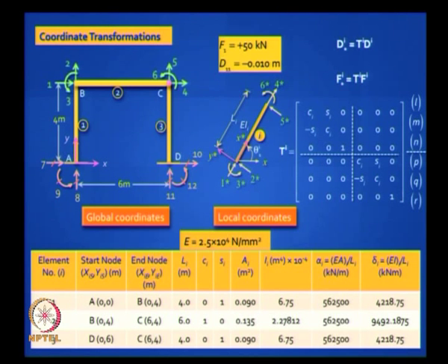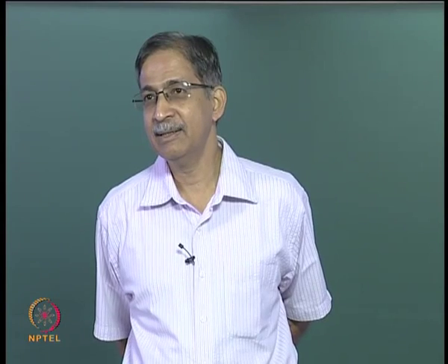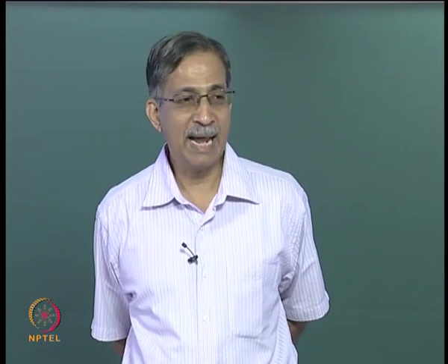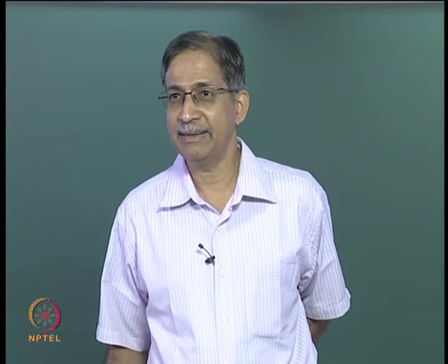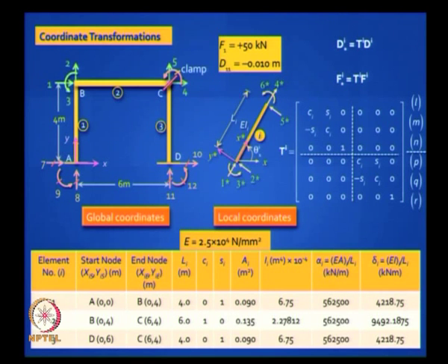So you see that hinge at C, and we are going to convert one of those degrees of freedom. Which degree of freedom? What's the number? 6. We convert it from active to restrained, and we introduce a clamp. So we do all that. Is it clear? That degree of freedom goes to the restrained category. Nothing else changes.